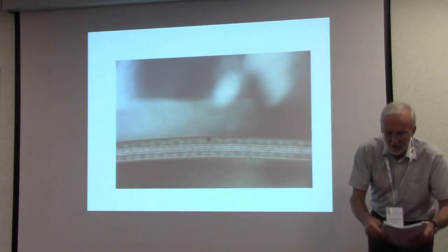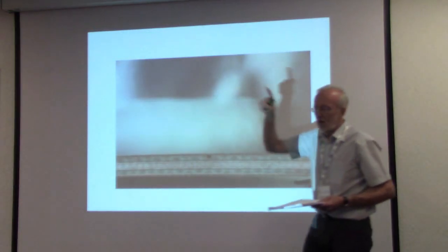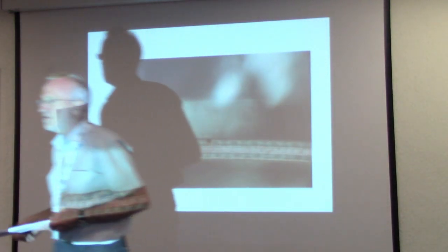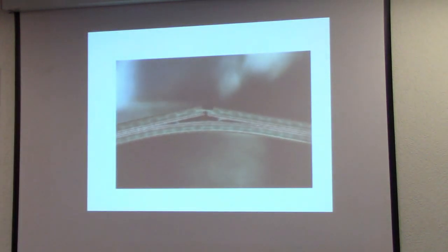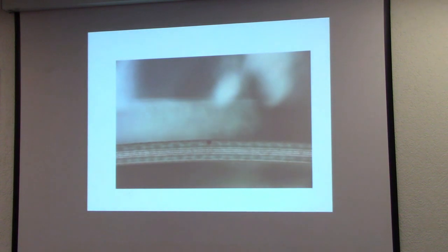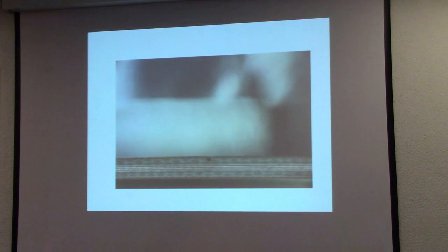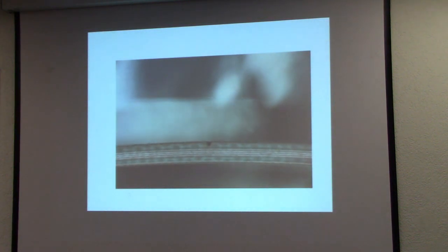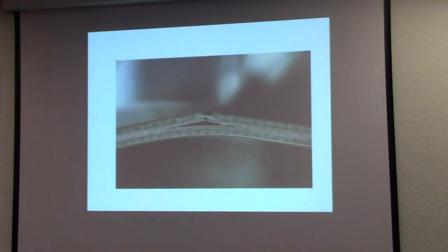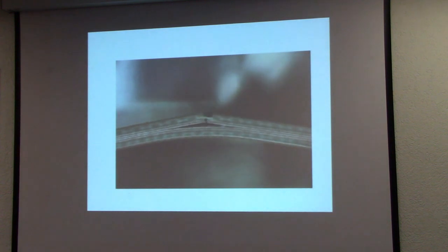If you have an ideal brittle fracture, even this telephone cord formation, the analysis, the fracture mechanics analysis, if you can do this in a linear elastic way, then it is in principle possible. The only thing is you have to take into account all the mode mixity effects in this case.